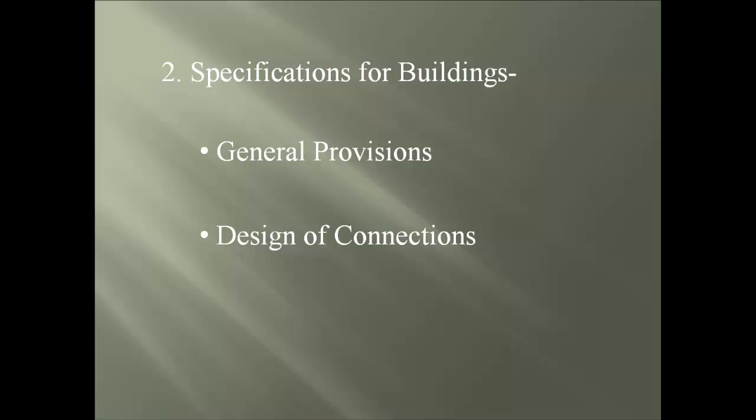Second item is the design of connections, covering both the simple connection of beams, girders, or trusses that are required to be designed as flexible and can react to shear only, plus designed for the rotation of beam ends, and also covering moment connections of restrained beams, girders, and trusses that are designed for both moment and forces from actions within the rigid connection.